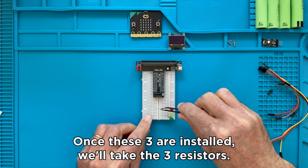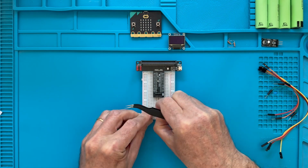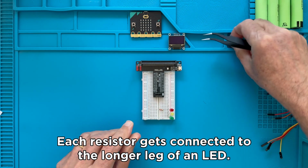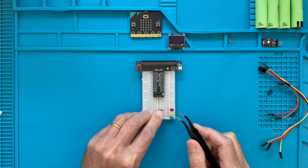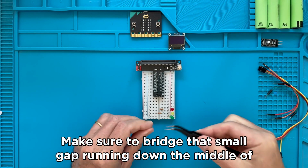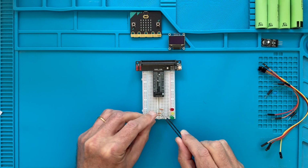Once these 3 are installed, we'll take the 3 resistors, and each resistor gets connected to the longer leg of an LED. Make sure to bridge that small gap running down the middle of the breadboard with these connections.